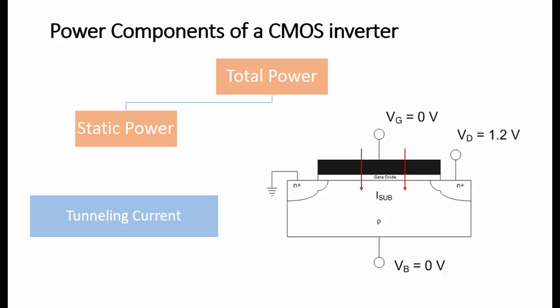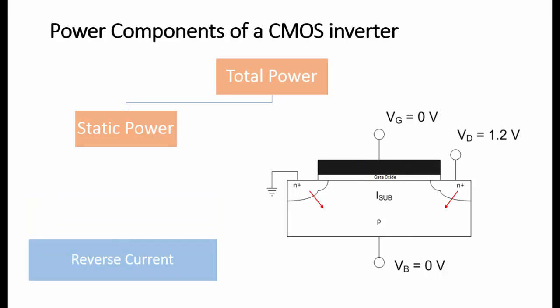However, with decreasing thickness of the insulator, the quantum mechanical phenomenon of electron tunneling occurs between the gate and channel, leading to increased power consumption. Increasing doping level allows higher on current for faster operations, but causes also higher leakage current. This produces a current of minority carriers, and hence its magnitude is very small.